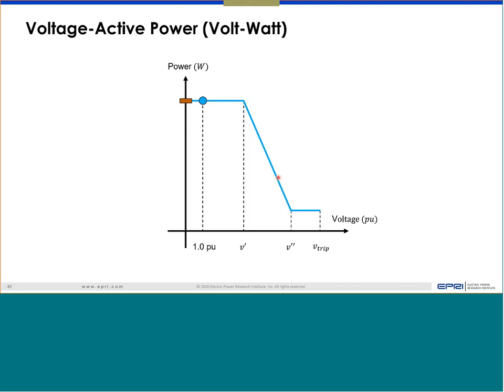This is not a direct curtailment. This is basically saying that at that voltage, you can export to the grid a maximum of that much. One option could be you do curtailment, or the other option would be you still generate and then charge your battery or use it in your load, as long as you don't inject into the grid. So that's the main idea of this function.